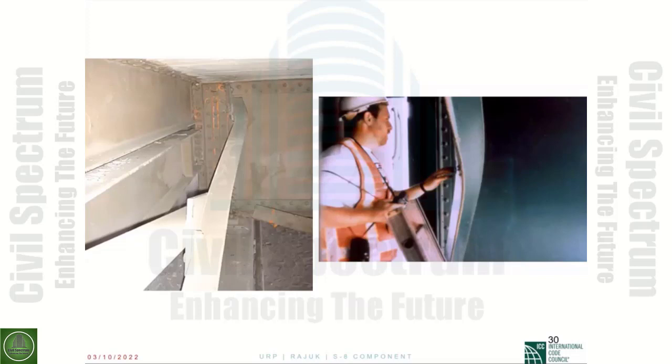And if you don't design them well, as you see here, they do tend to yield or buckle or even fracture if they are not detailed well based on B/T ratio and local buckling effect.